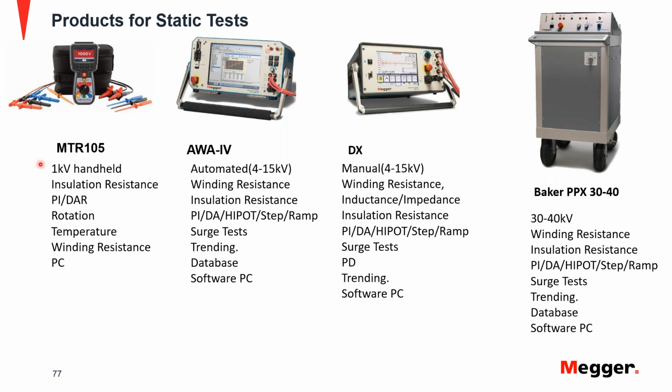Here we have the MTR 105, which is a handheld device that allows us to do Megger tests, and then it also allows us to do winding resistance, rotation, allows us to do polarization index and electric absorption ratio. It's a fantastic tool in the hands of technicians. It has an input for a thermometer. You can measure the temperature. It has alarms. It can download the results to a USB, and then you can import them into a PC with PowerDB and use the results right there. It has everything but a surge tester.